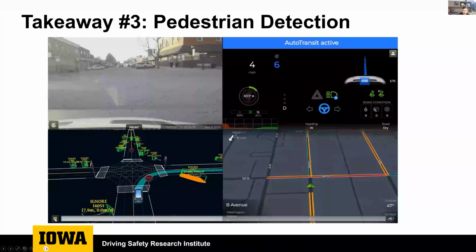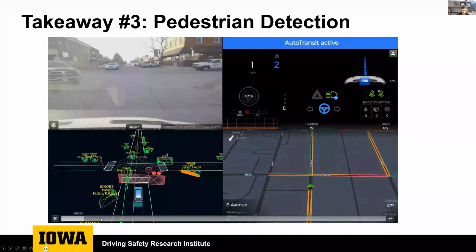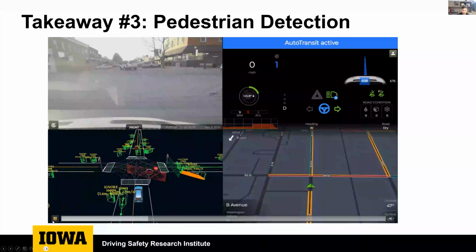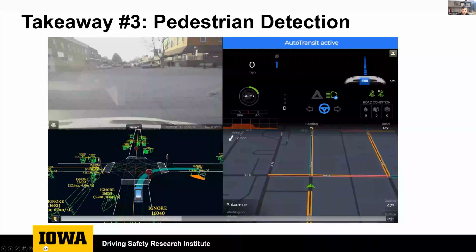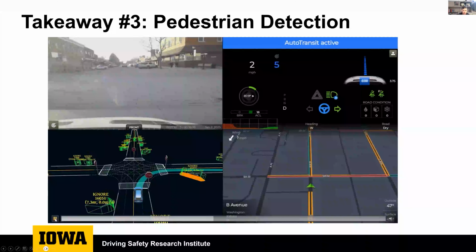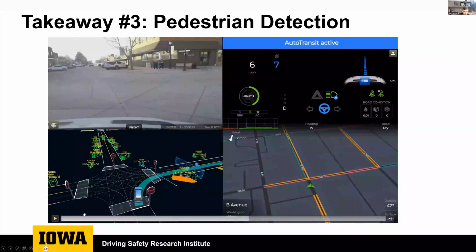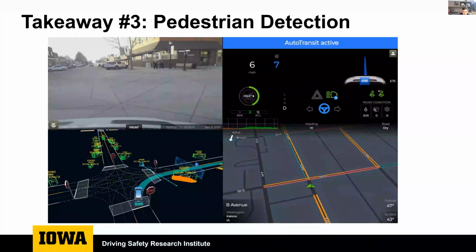So as the pedestrians get closer to the intersection, you notice they start getting picked up slowly, with the transit LiDAR having issues distinguishing between them and other objects around them, so they begin popping up yellow and blue. Right about there is good. So here you'll see those pedestrians are classified as a blue object in the bottom left Apollo view.